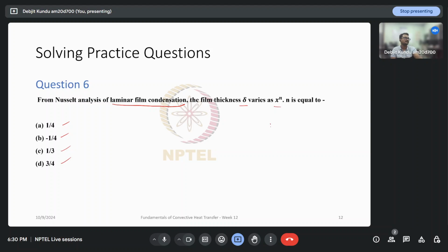So what we did here is that we had a vertical film like this, or a vertical surface like this, which was cooler than the vapor on the other end, and it did not lead to drop condensation, but rather it led to film condensation, and that film started flowing downward along with more condensation happening.